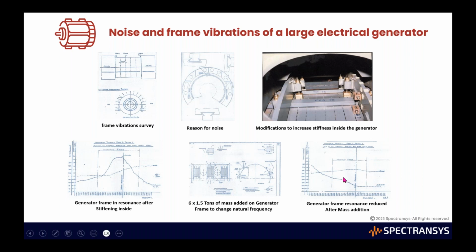Because you are increasing the mass, reducing the natural frequency. It has got down well below the operating speed there. So this is one case where we would like to present, involving the design and engineering stages and all those things. Actually, probably nobody knows really what happened, where it happened, and all those things.